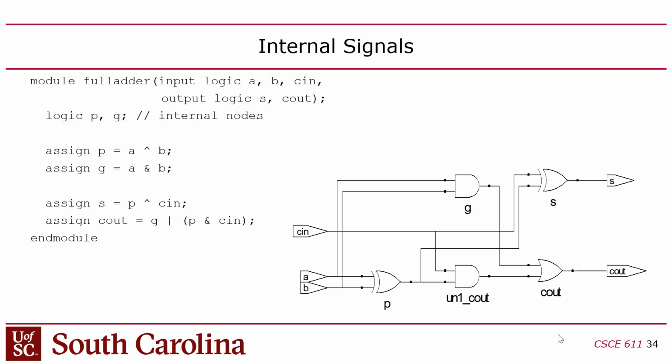Because what's happening in here is that if the inputs A or B change, it causes a triggering event that updates P and G. And then if those change, it will subsequently trigger these two other assigns that depend on those two guys, right? But you can take these 4 lines of code and scramble them in any order, and it won't change the behavior of this module because each of these 4 assignment statements is set up as a trigger. Anytime their inputs change, the outputs are updated, regardless of what order they're in in this file. Does it make sense? Okay.